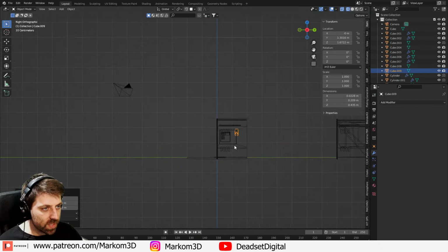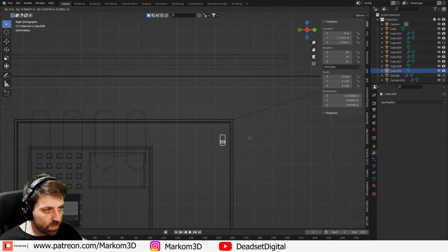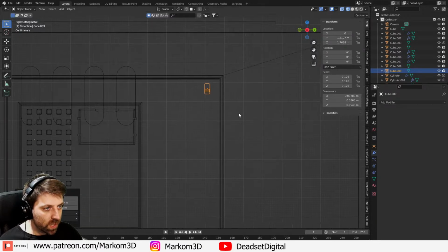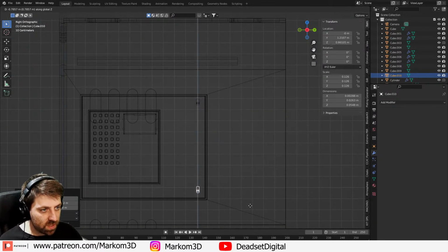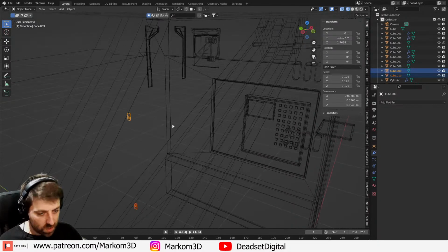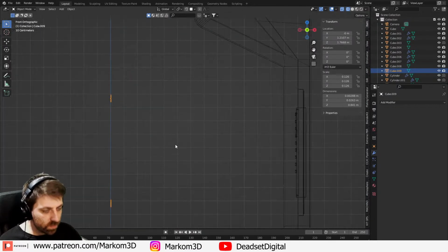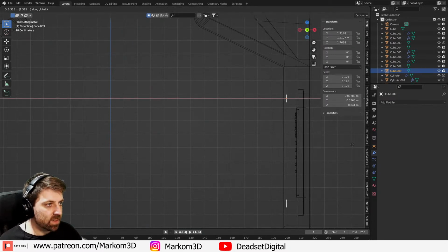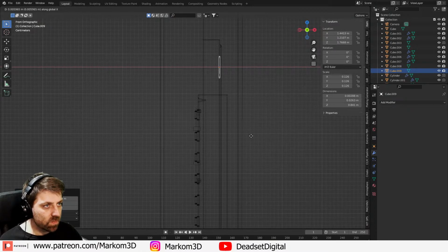So when we bring that down, it's a bit of a gigantor. I'm going to put one here. Shift D, Z, rotate 180. Let's go Control J to join, because we can. GX, and it's kind of like, yay, well done.